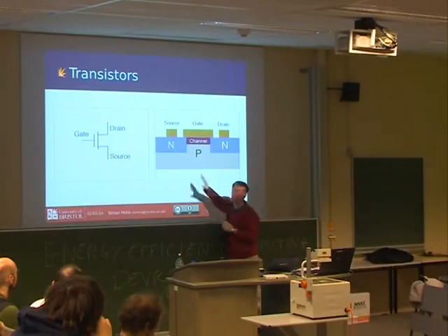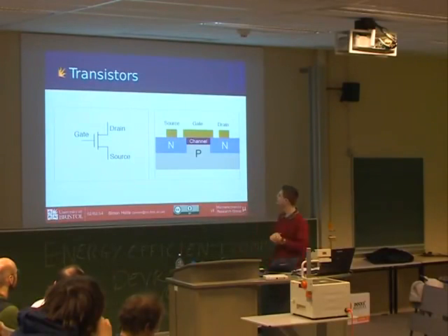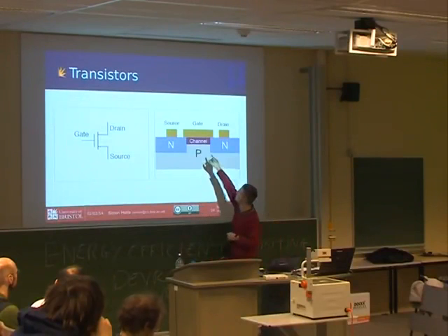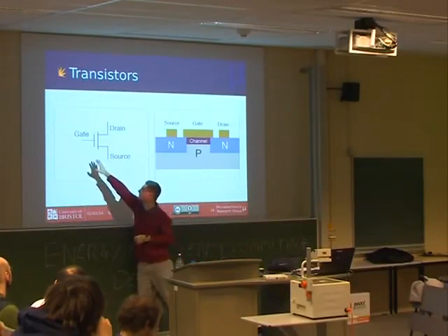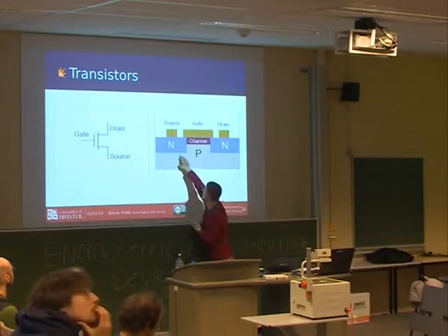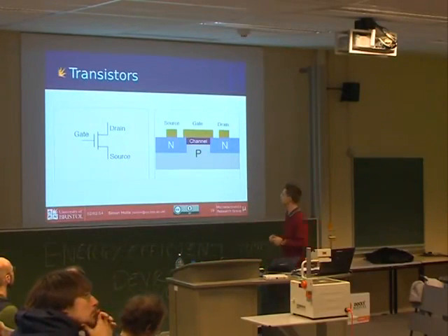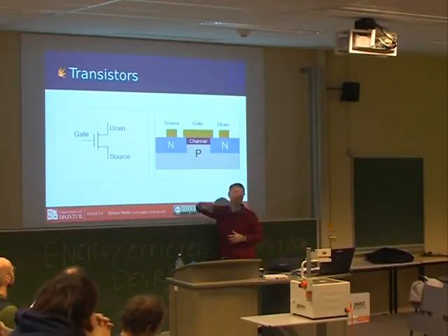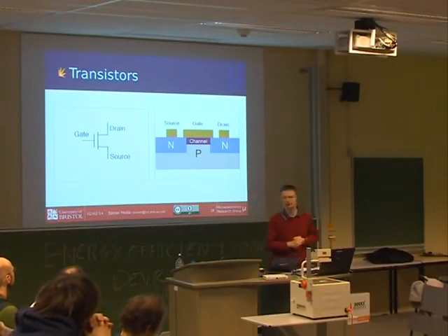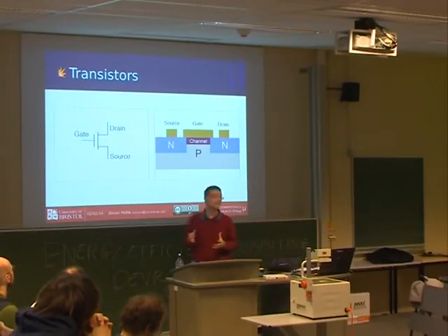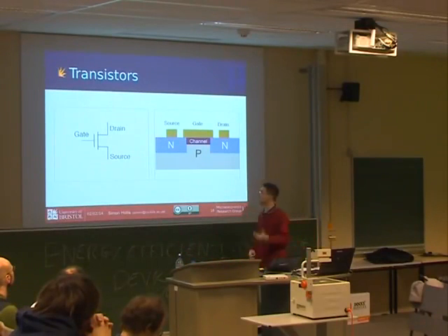So we've got two different types of silicon, two dopings of silicon here. And the idea is that this transistor will be able to be switched according to a voltage on the gate here, and if it's switched on, current passes between these two blocks of N-type silicon, and when it's switched off, current's not able to pass through that area called the channel. So this is a device you can turn on, you can turn off based on the voltage on the gate. And if you move the voltage on the gate, you will dissipate power.